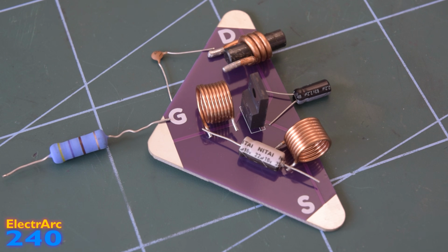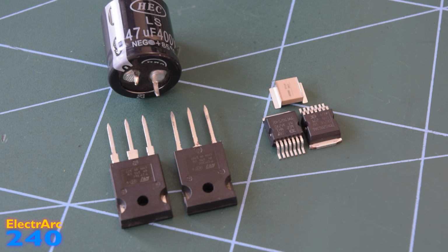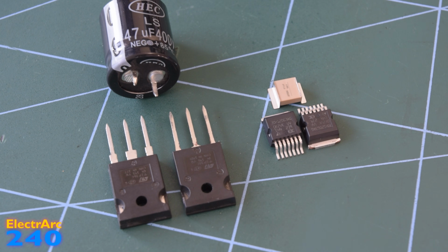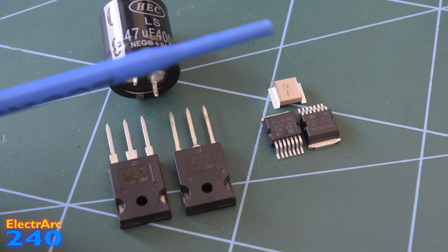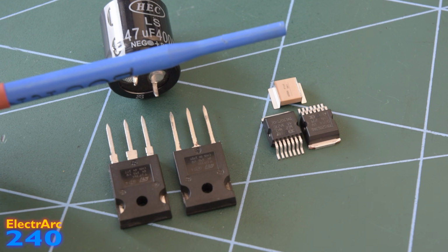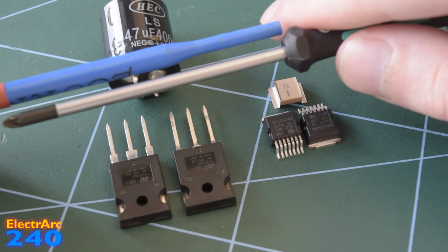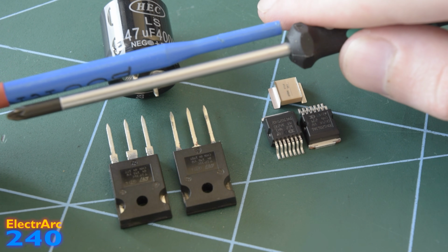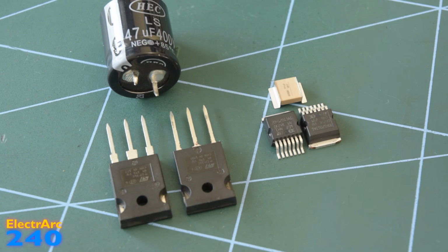Next, as I showed before, especially for a half bridge, loop area should be kept as small as possible. This applies not only to the power loop, but also to the gate drive loop. And an easy way to keep these areas small is to put opposing current paths on different layers of the PCB. So for example, for the gate drive, you might have your trace connecting the gate to the gate driver on the top layer. So then all you need to do is run the source trace back to the gate driver in parallel on the layer below. And you can see now the area between these two is very small, which means the inductance is very small.